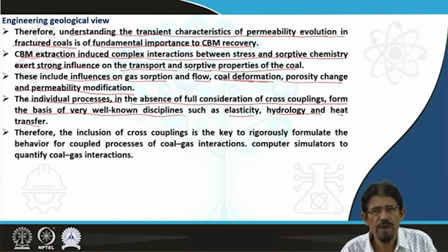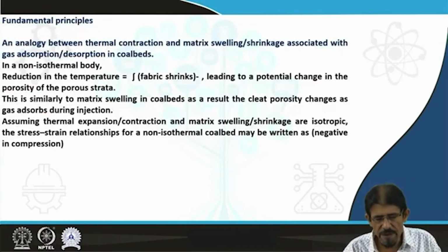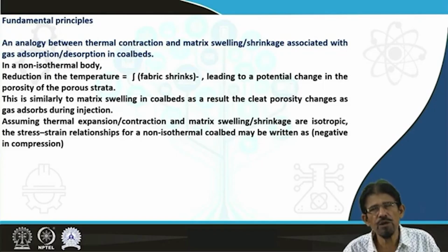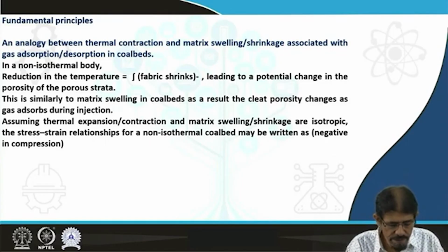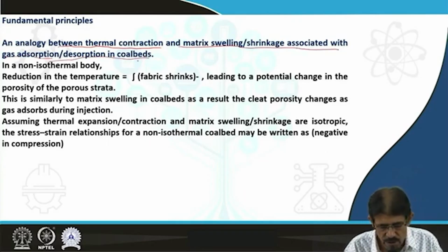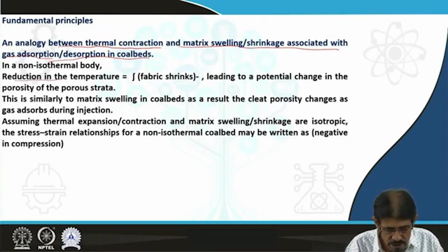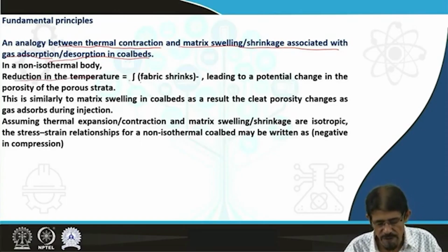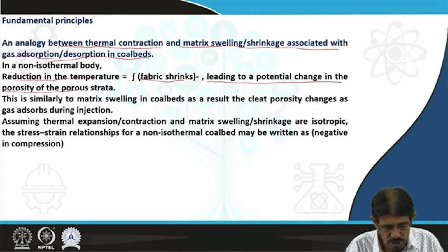Fundamentally, we can utilize the principles of elasticity and mechanics in analogy between thermal contraction and matrix swelling and shrinkage associated with gas adsorption and desorption in coal beds. Following classical mechanics, the reduction in temperature is a function of shrinkage, leading to a potential change in porosity of the porous strata.